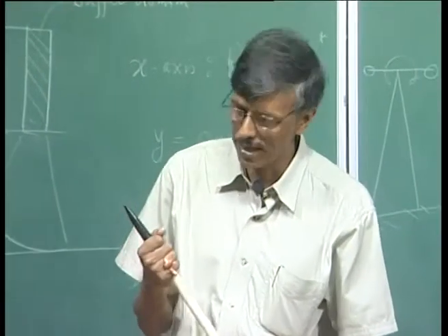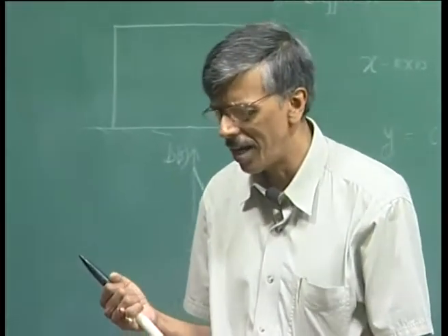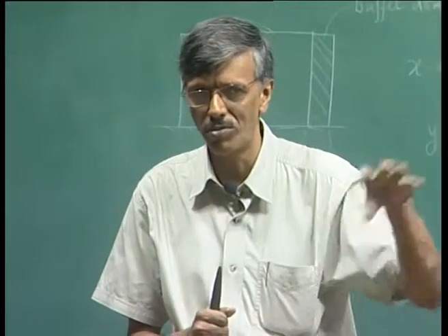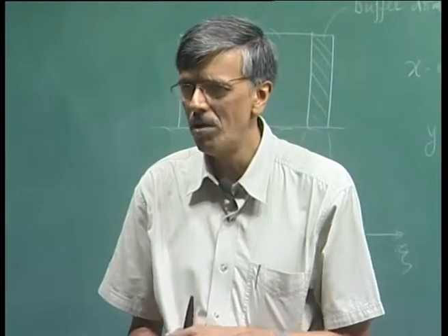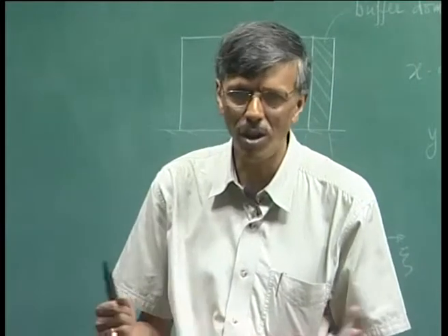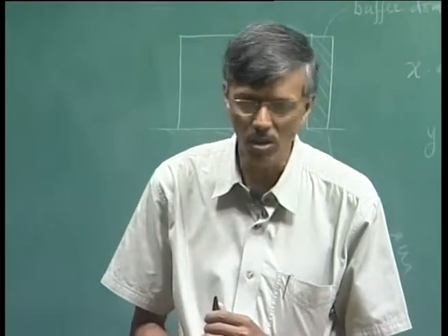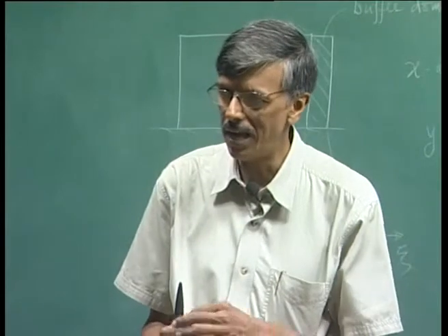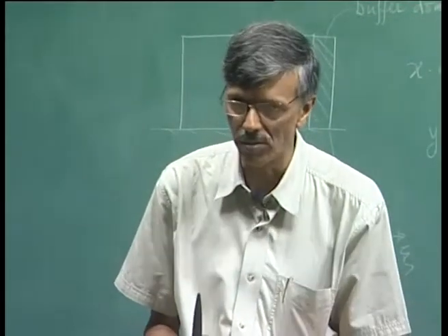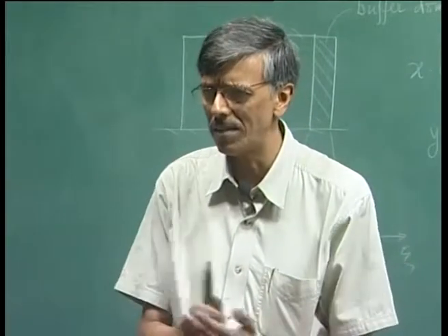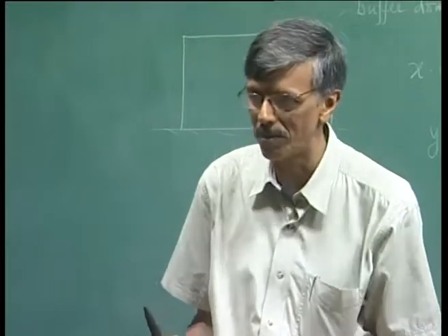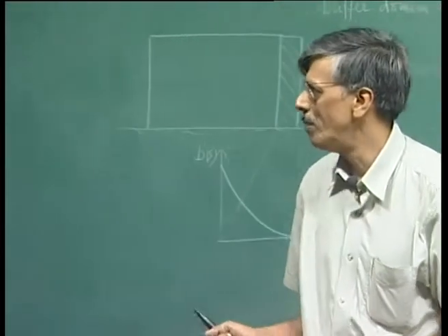What he meant was that there are all these nice lab experiments where we demonstrate Tollmien-Schlichting waves, but there are many flow situations where Tollmien-Schlichting waves are not at all relevant, and they are undergoing transition due to some other mechanisms. So all these other mechanisms taken together, he coined as the bypass mechanism.